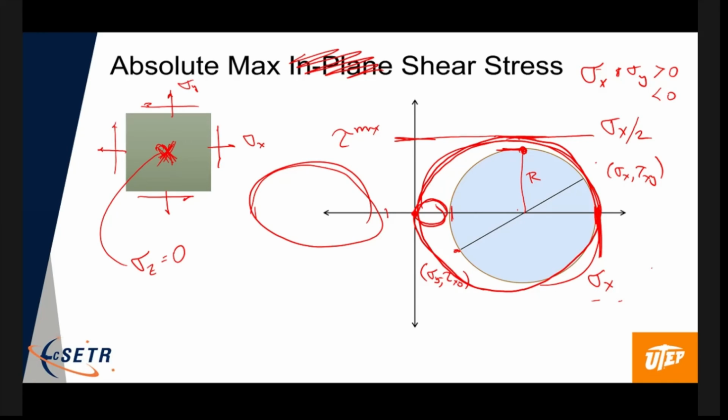That's actually the maximum value of shear stress for that material, and it actually is a rotation that's not quite in the plane. It also involves a little rotation out of the z-axis. It's a little difficult to visualize, so we don't really go through it, okay? But if you have both normal stresses, either positive or negative, that's the case.